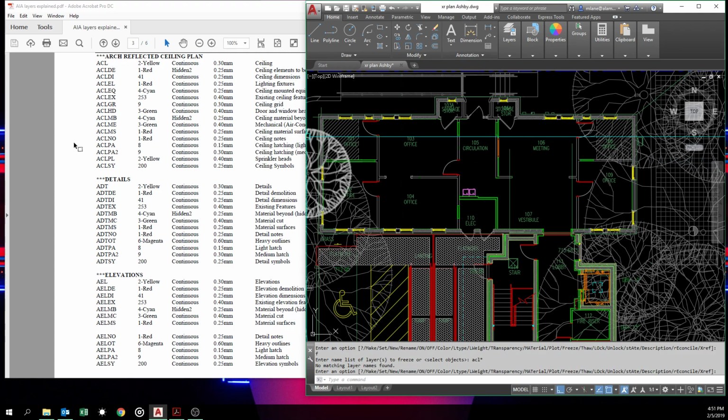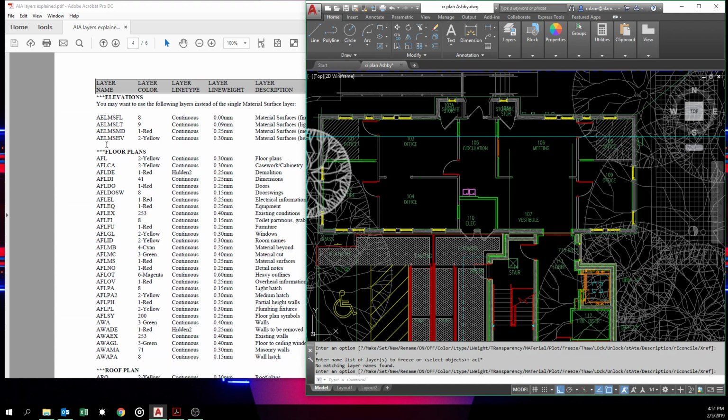That's why this layer list is useful. We could have just called this, like, let's go to the floor plan, because most people are familiar with those. We could have just called layers cabinets, doors, door swings, electrical. But then, in order to freeze and thaw these layers, we have to come in here and pick one at a time, and it takes forever. So having that ability to control them helps. Anyhow, just some advice on the AIA layer system.